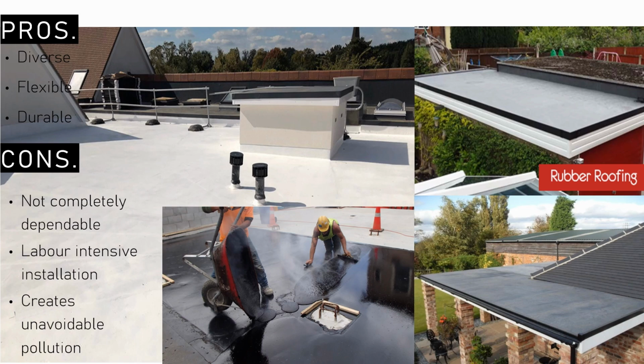The mastic asphalt also has high durability and has been successfully used to provide unbeatable protection from water penetration for over 150 years. However, despite the waterproofing membrane having high durability, other elements of the system may fail over time and require full replacement, implementing the renewal of the waterproofing membrane as this has been melted into place initially.